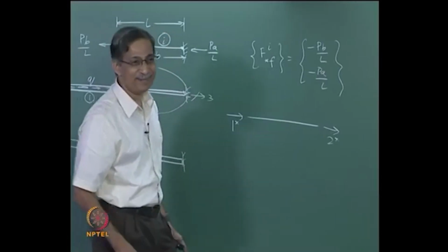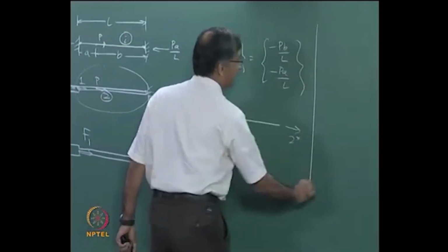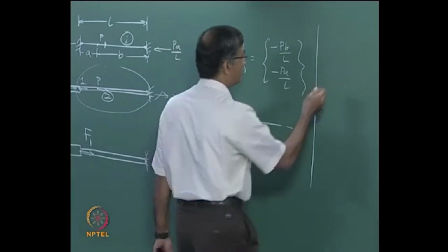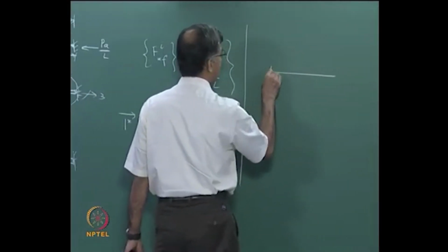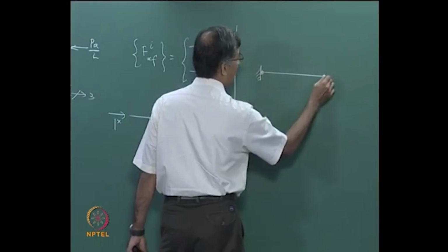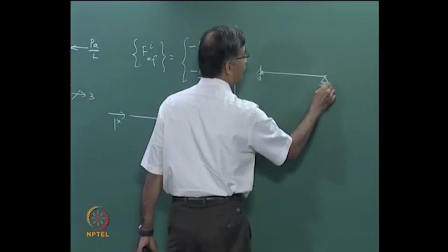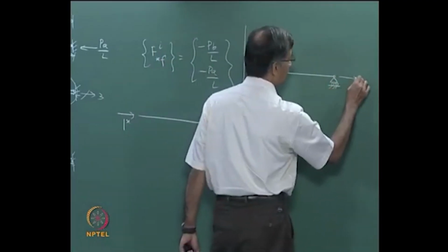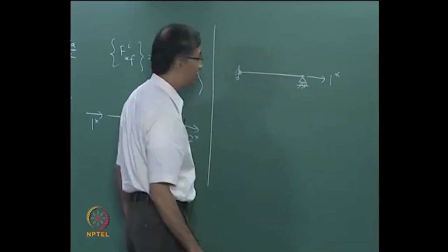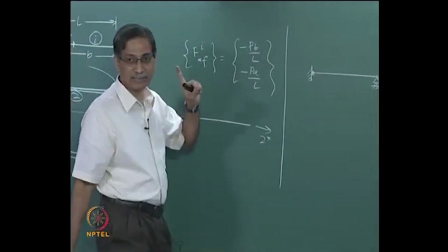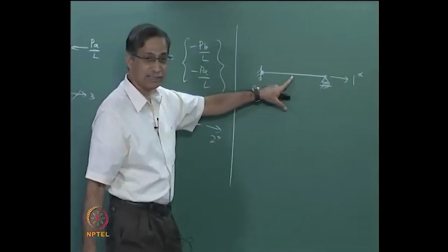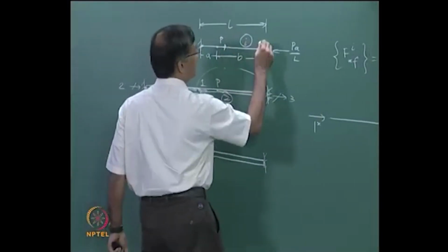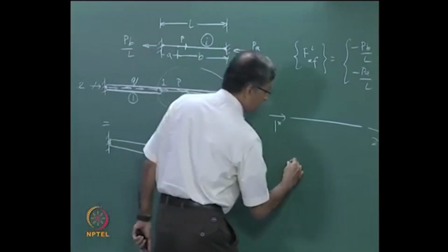But now we have a problem, because we have, unfortunately, in the reduced element stiffness method only 1 degree of freedom, and so our element is like this. We say we arrest this, this is pinned, and maybe you can, since you were uncomfortable in the last class not having a support there, put a support there, right, and this is 1 star. So I do not have 2 numbers here, I just have 1. And what is the axial force in this due to this? I have a problem, because the axial force in this element actually has a variation, right.